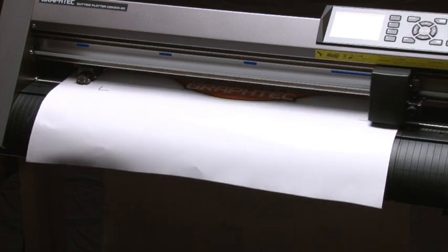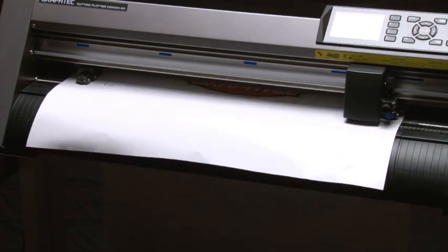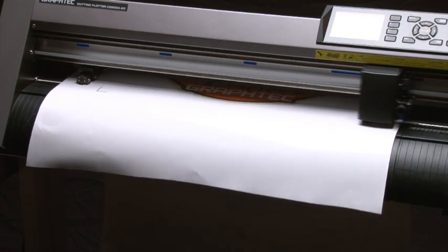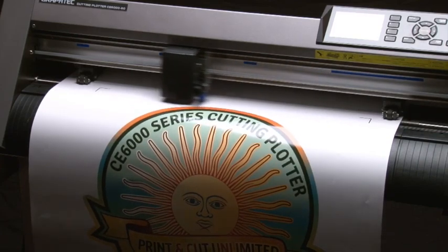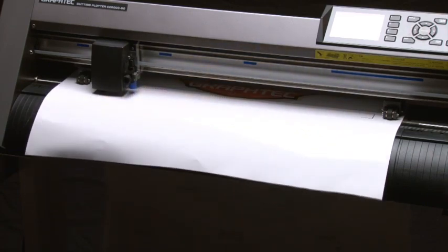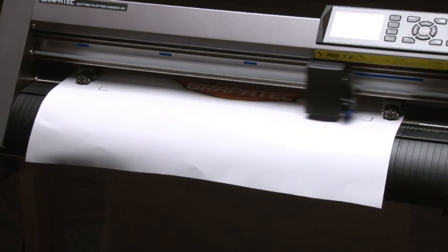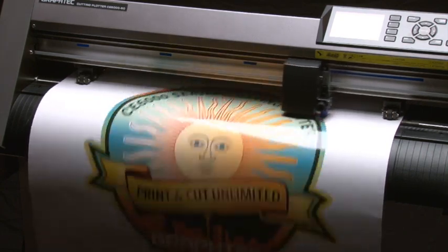Once the job is sent, the sensor will start scanning the first mark. If for some reason it cannot find it, it will go searching for it. Once it finds it, it will continue on to the second mark, and so forth. Since it knows the location of the other registration marks, it doesn't need to do a search pattern, thus saving time. Once all the marks are found, it will start to cut the media following the adjusted cut path.